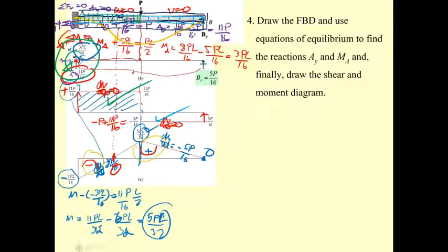Also, if you like, you may determine the position for this point. Like I said, this is the inflection point. This is very important because it's the point that changes the moment from positive to negative, and the point where we change the reinforcement from negative on the top to positive on the bottom.